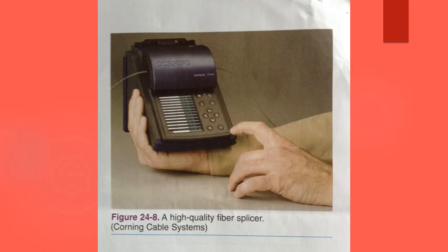A glass core fiber optic cable is cleaved, not cut, like a regular wire conductor. To cleave the fiber core, it must be scribed with a sharp cleaving tool edge made of diamond or ceramic material. Once the core has been scribed, pressure is applied to the scribed area until the core breaks. The scribe and breaking action produces a clean, clear surface at the end of the core. Traditional cutting tools used for wire cable would badly scar the ends of the core. Figure 24-8 shows a high quality fiber cleaver.